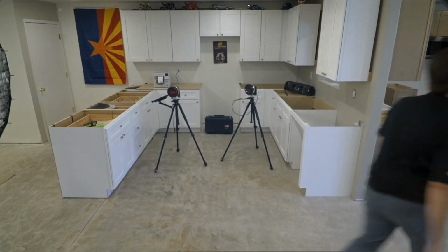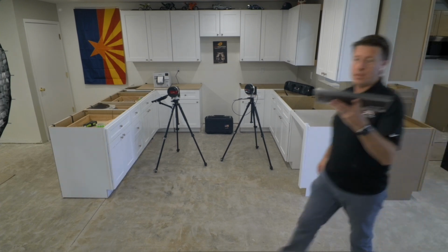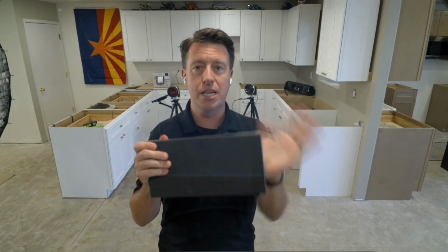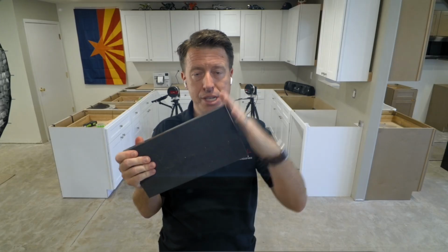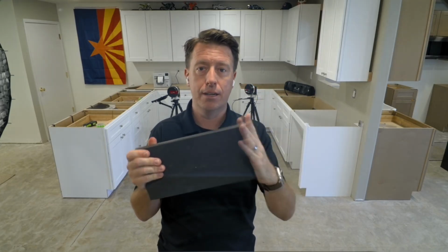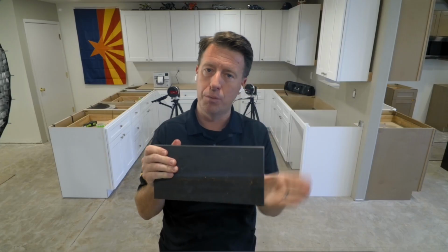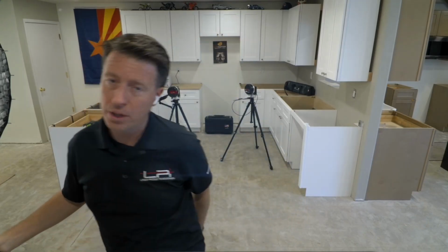Let me go off screen here. Just a little sample piece, right? If the saw was going to cut a specific size and it's going to go on the router, the router will finish each side and have to take material off. So now on the saw, we need to make that bigger everywhere so the router can remove that. So we're going to add that into our workflow today, okay?